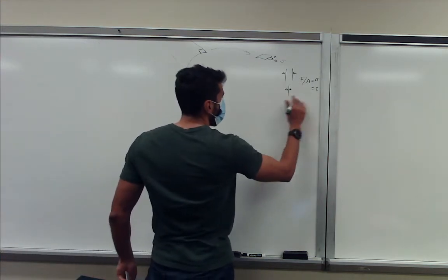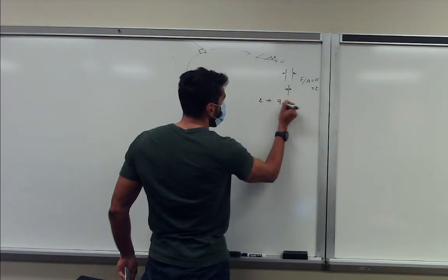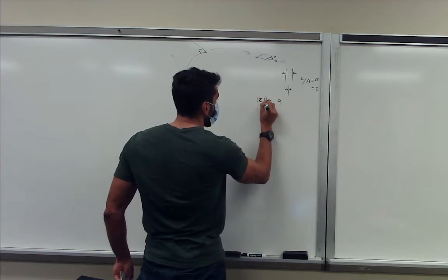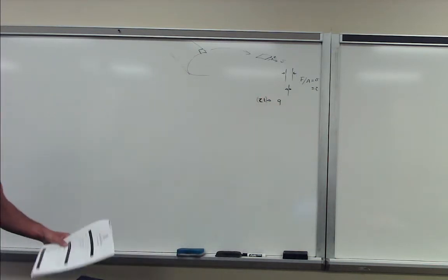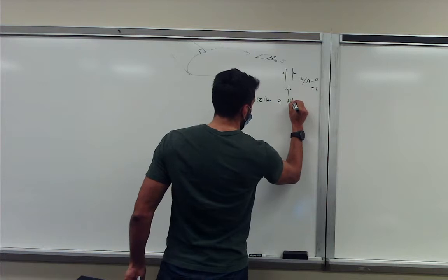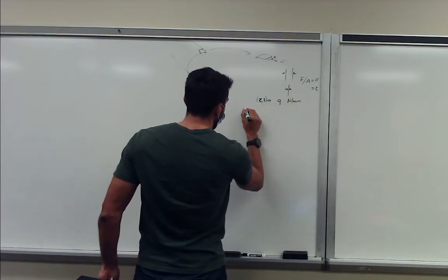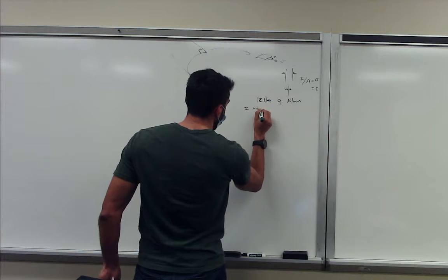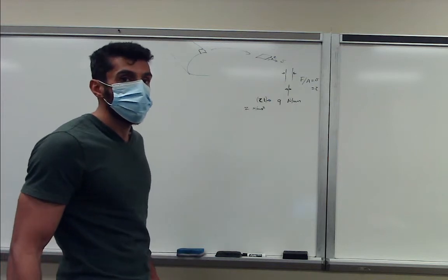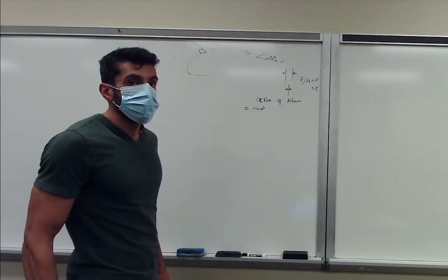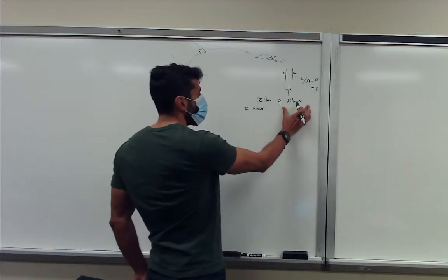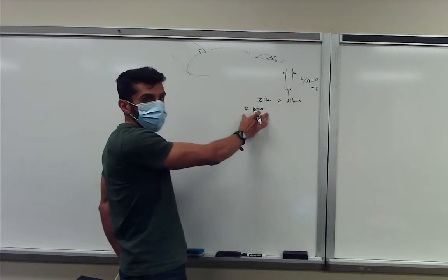So we move away from our stress convention, and we said we're going to go to a shear flow convention, and we assume that the shear stress multiplied by the thickness is our shear flow. So the shear flow has Newton per millimeter, instead of our shear stress that was Newton per millimeter squared. Yes? So it has the same unit as the general stress distribution, so we could maybe treat it that way. No, the unit is definitely different. So this is per millimeter, or per unit length, and this is per unit length squared.